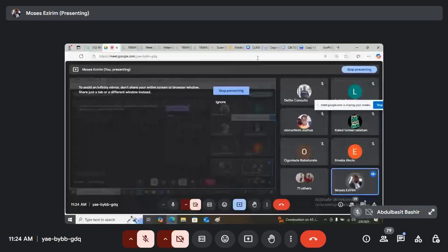You can also go with the monocrystalline. This is because I realized that along the line there can be some shading. Obviously, when you do your plus and minus and you realize that no. For example, now if I'm doing an installation in a place that I know is a bit dusty, I can decide to use half-cut cell. But I can use half-cut cell if I've done my financial model and I realize that I'm good to go, then I can do half-cut cell.